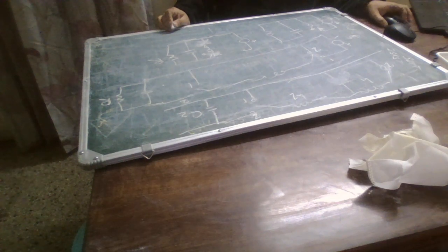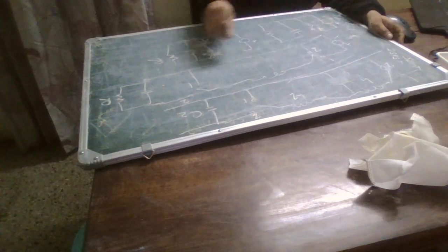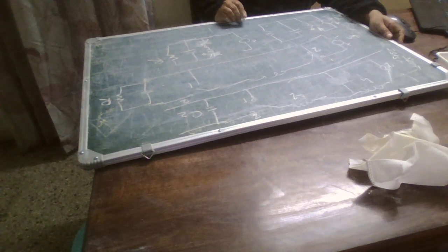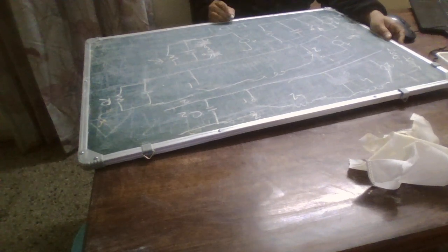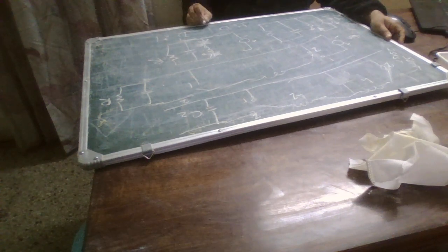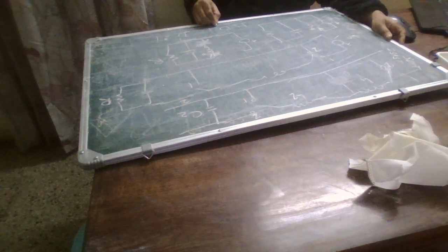Now we can very easily see that once we are connecting it, what we have basically got is that we have cascaded the buck and a boost, buck followed by a boost. If I recall, in the buck video I have mentioned that the buck is basically an equivalent DC transformer. That means I can have an equivalent model with a 1:D transformer ratio, and for the boost it's D dash is to 1. So we are having a transformer.